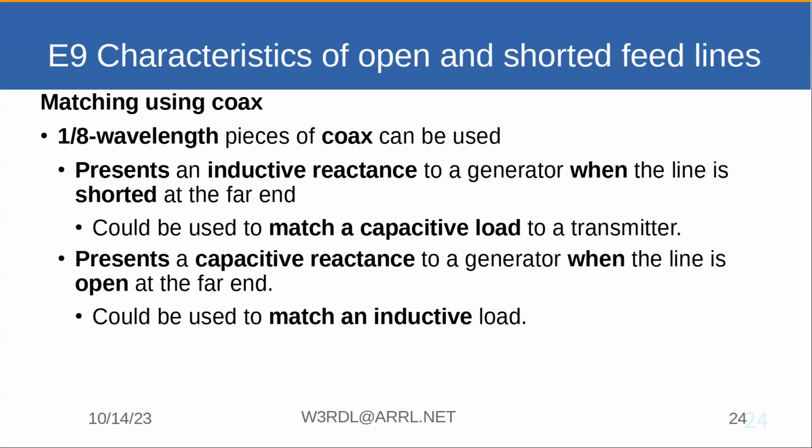So, to my mind, that only lets you offset a certain amount of inductive reactance at that frequency. And if that's how much you need to offset, that's fine. But if your antenna is much more capacitive than that, it's not going to get better. It could make it better, but I don't know how you can say it matches it unless you were lucky.